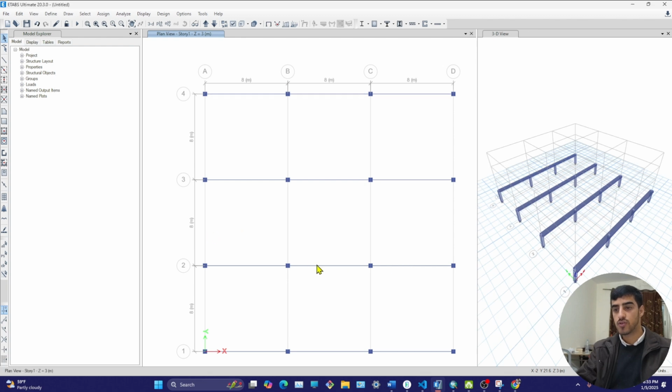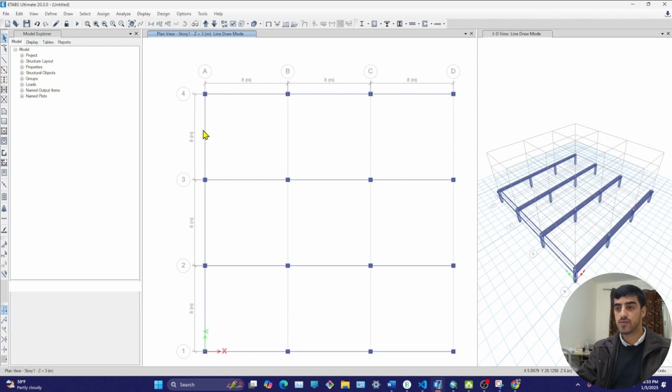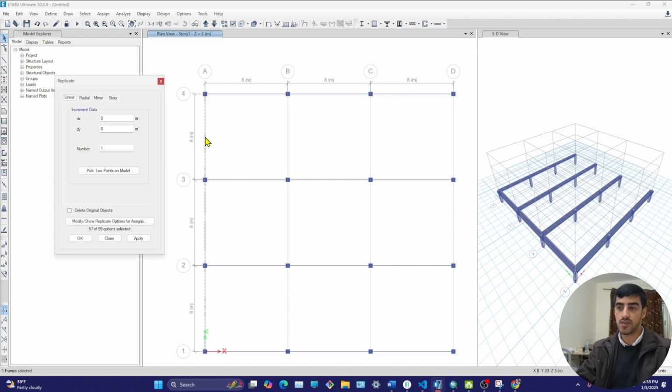Perfect. Now we have drawn in the X direction. Now we need to draw the beams for the Y direction. Also from the bottom to the top. The methodology is very crucial and important in design, and the analysis results would be different if you didn't follow this strategy, because the mesh and the analysis would have a lot of issues.